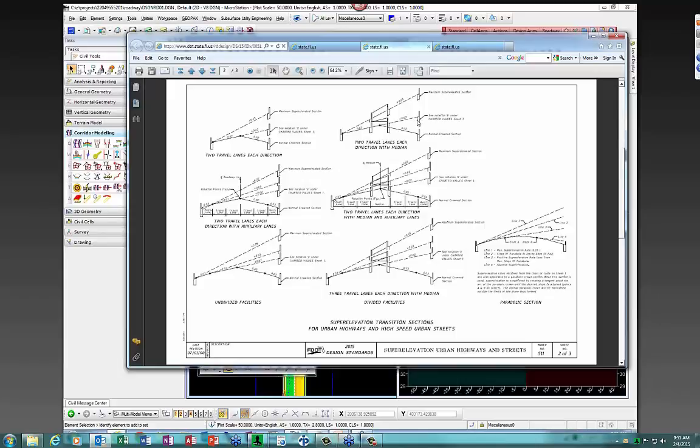If I had used a design speed of, say, 45, it would have to have gone up to probably 27, 28, and in which case it would have had to rotate everything from the inside. Okay? If you know you have that situation once you calculate it, then what you've got to do is set your lanes up from the inside out. But because I was going to rotate about my pivot point, I didn't have to necessarily worry about it. I set my lanes up from the pivot point out, left and right.